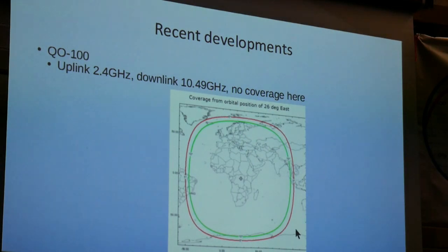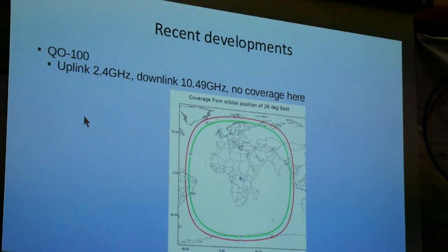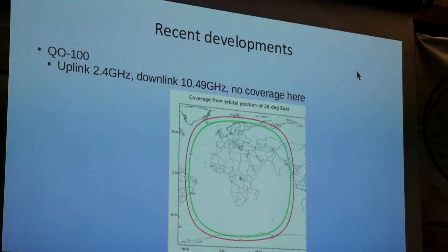There's been a lot of innovative stuff done with people in Europe on this. It's just magic. It's just a single channel. Well, it's an 8 megahertz channel, which means you can fit in a whole load of TV channels at the same time. You don't have to. I mean, this is all narrowband stuff now, so it's typically 333 kilo. It's all DVB-S, by the way. Nobody runs DVB-T on this satellite, but you can get about 8 narrowband DVB-S channels in here, and more even smaller ones.